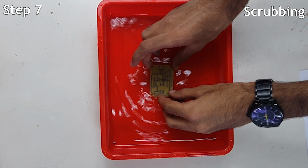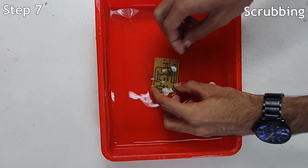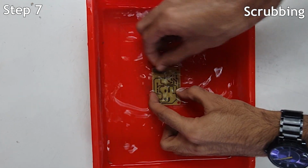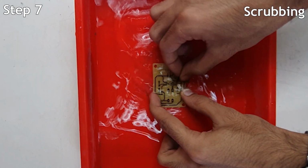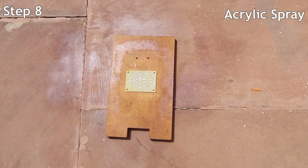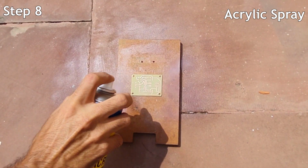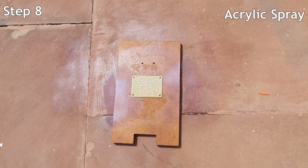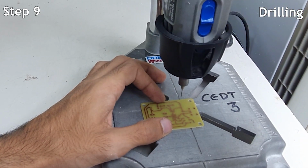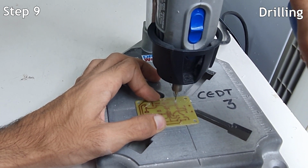Step 7. Scrubbing. The remaining toner is removed from the surface of the PCB using an abrasive scrubbing process. This ensures that the copper traces are clean and ready for further processing. Step 8. Conformal spray. A conformal coating may be applied to protect the copper traces from oxidation and environmental factors. Step 9. Drilling. Holes are drilled into the PCB to accommodate component leads and mounting screws. These holes are strategically placed according to the design's requirements.